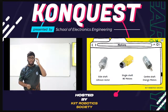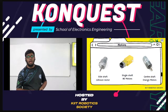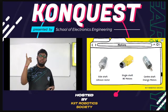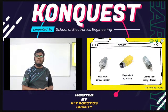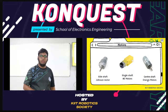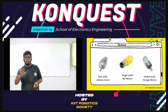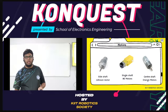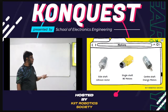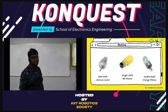So the normal BO motor is very popular among beginners. But the problem with BO motors is that they have very low RPM, and with low RPM they don't have any torque either. So they are not capable enough to tackle the obstacles coming into the arena. So we are not recommending going with BO motors. The other one we can easily find at local vendors is the Johnson side shaft motor.